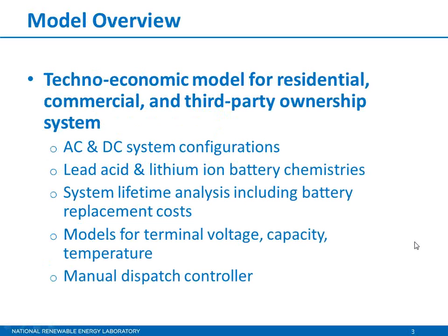So what is the battery model in SAM? It's a techno-economic model that basically allows you to model batteries and their chemistry for different kinds of financial systems, including residential, commercial, and third-party ownership. You can customize whether the battery system is connected on the AC or DC side of the PV system. You can choose between lead acid or lithium ion battery chemistries. And a particularly powerful feature of the model is the ability to do the system lifetime analysis.